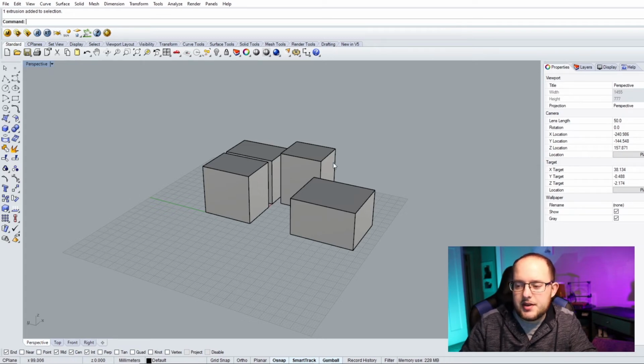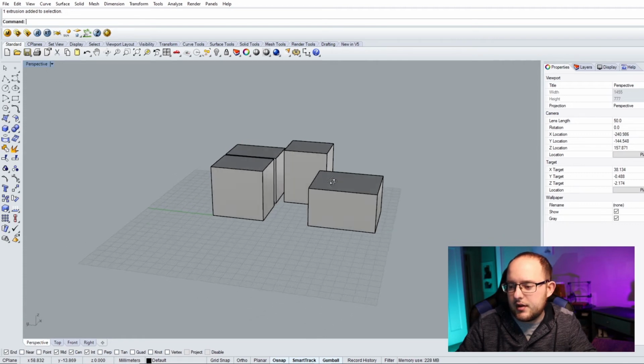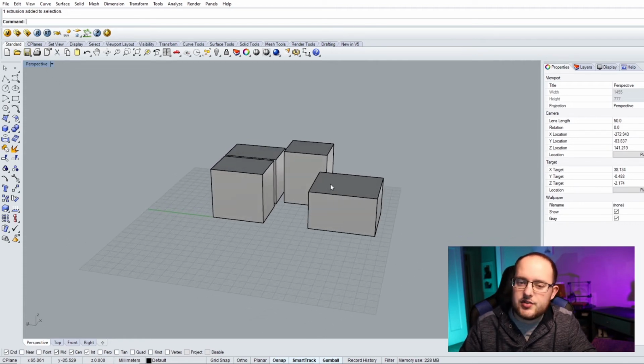It'll make your life easier in the end, versus getting hours down the road, having made this amazing model, and then it's not watertight, it's not a usable 3D print. It can get messy to clean up later. So just try and model as efficiently as you can, and trace your steps to where you could have gone wrong with a model becoming not watertight.